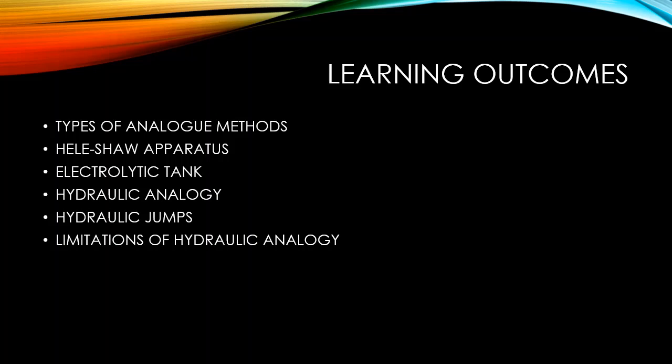respect to different domains. Let us have an example. If we are going to test any kind of object inside the wind tunnel, which is blown with air, and we carry the same model inside a water tunnel, where a water stream is there, the properties are different. With the help of this analogy method, we are going to equalize both the wind tunnel properties as well as the water tunnel properties.